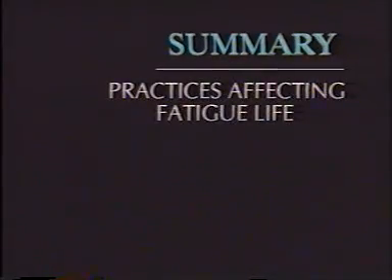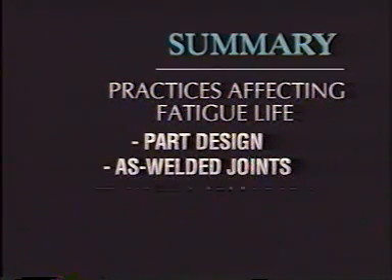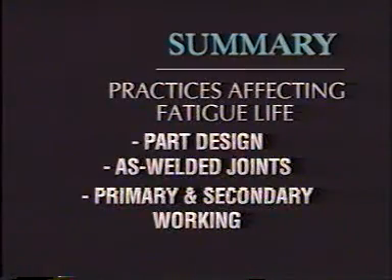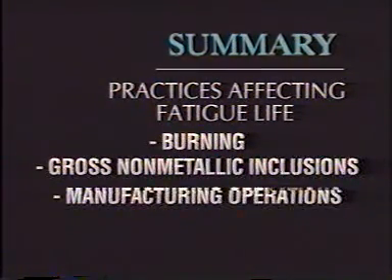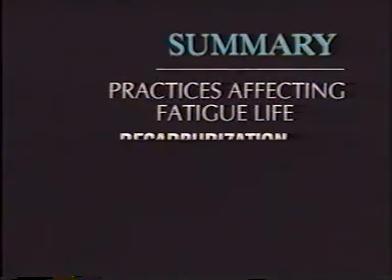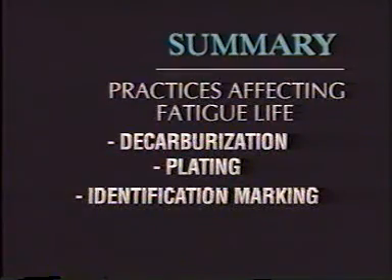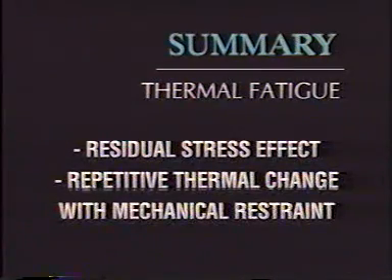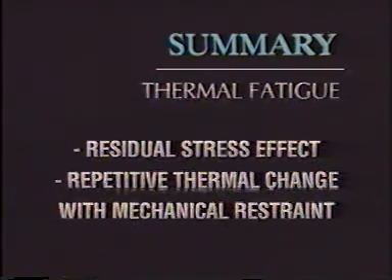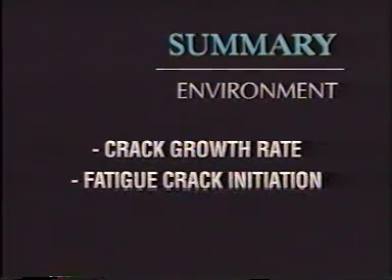Summary: practices affecting fatigue life. Part design, as well as welded joints, primary and secondary working, burning, gross non-metallic inclusions, manufacturing operations, quenching, decarburization, plating, and identification marking. Thermal fatigue is a residual stress effect. Principal cause: repetitive thermal change with simultaneous mechanical restraint. And finally, environment will affect crack growth rate and the probability of fatigue crack initiation.